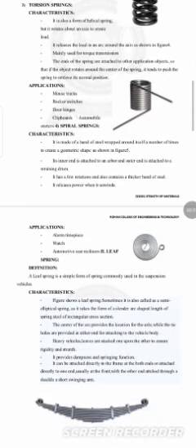Then spiral springs. Character: it is made up of a band of steel wrapped around itself a number of times to create the geometric shape as shown in the figure. Its inner end is attached to an arbor and the outer end is attached to a retaining drum. It has a few rotations and also contains a thicker band of steel. It releases the power when it is unwound. The applications are watches, automotive, seat recliners.